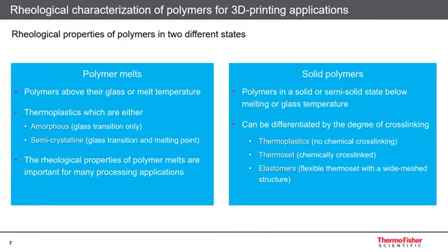Thermoplastic materials are not chemically cross-linked, and the process of liquefying by heating is reversible. However, if the polymer is chemically cross-linked, we distinguish between thermosets and elastomers. Elastomers are rubber-like materials that have, compared to the stiffer thermosets, a significantly lower cross-linking density. Elastomers and thermosets cannot be converted into a free-flowing melt due to the permanent chemical links between them.